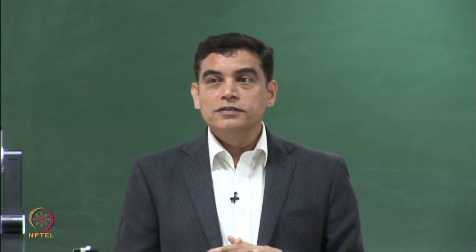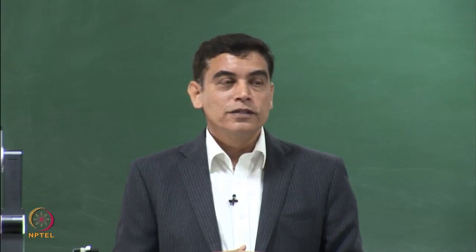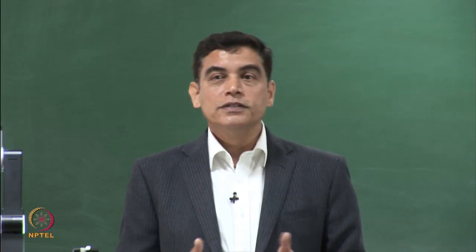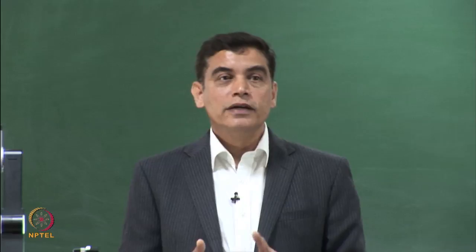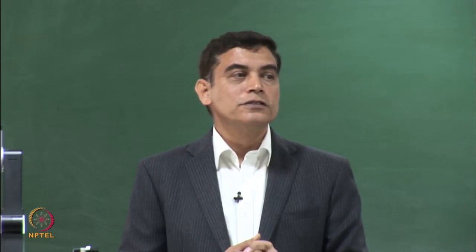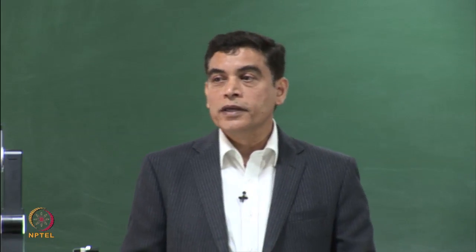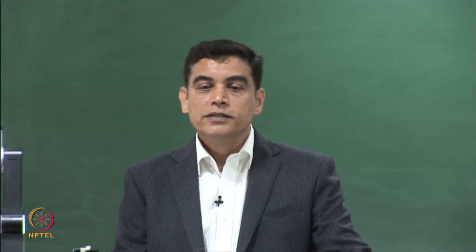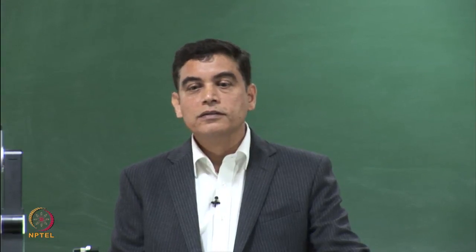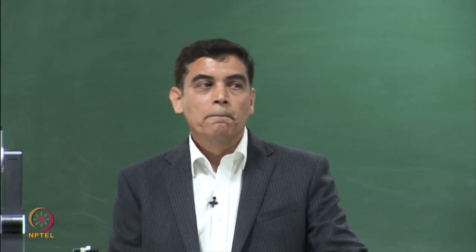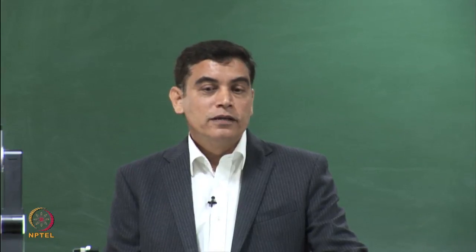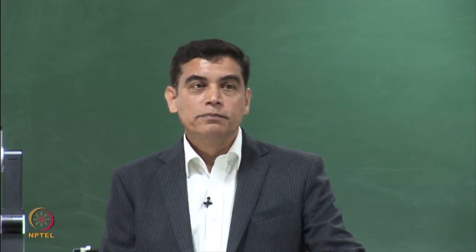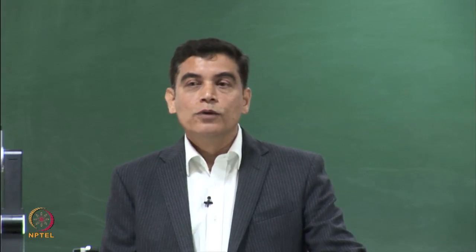It's important to voice some of these concerns when you are in a place where you can exert influence on the authorities, you talk to people, because overall each one of us is impacted, sometimes directly or indirectly, by these limitations. So let's say today you go and buy an air conditioner, and if you don't have thorough knowledge about standards and about risks of refrigerant toxicity, you might easily buy a propane air conditioner, and someone might use an opportunity to just do a trial, and it may work fine for many years until there is a leak. And if the leak were to happen at a time when you are asleep, think about what can happen.